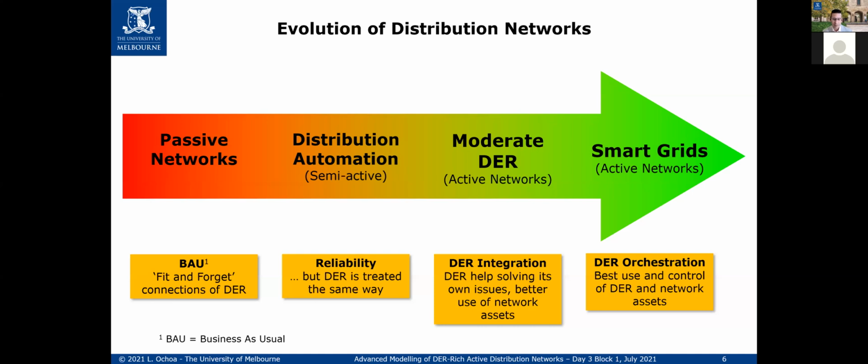So if my requirements, in my part of the world, say that every 10 minutes my voltage has to be within this limit, then my control cycle will have to be perhaps just a little bit less than 10 minutes, right? Certainly no more than that, because I might not hit the target. So it really depends on that. It's not that everything has to be done every second or everything has to be done every 5 minutes. It depends on how things are assessed in each country because of the different local requirements, okay?